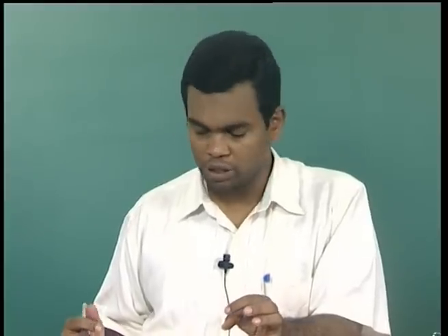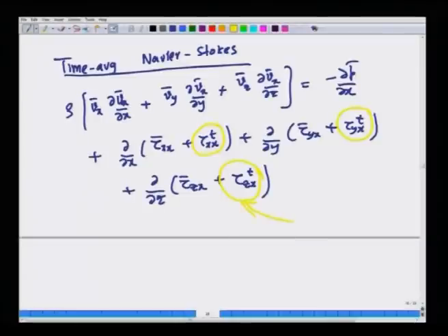So, even though you are trying to average out the fluctuations and write equations only for the mean flow quantities, that is the time average quantities, the fluctuations do come in indirectly through the time averages of the correlations. This is specifically because of the fact that the Navier-Stokes equations are nonlinear. If there are no nonlinearities, then you will not have these extra stresses, these turbulent stresses. So, this additional transfer of momentum comes only because of the convective nonlinearities in the Navier-Stokes equation. Okay. Now,